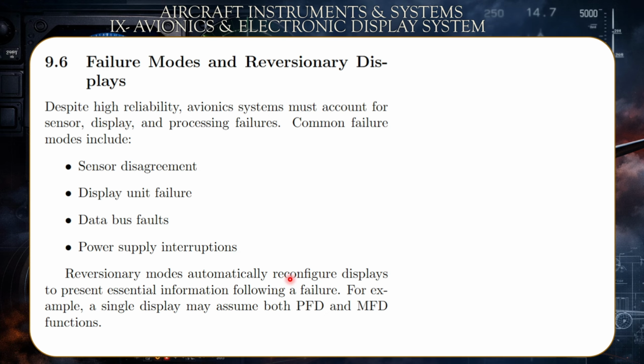Reversionary modes automatically reconfigure displays to present essential information following a failure as a backup. For example, a single display may assume both PFD and MFD functions. Okay, it can integrate both PFD, primary flight display, and multi-function display functions.